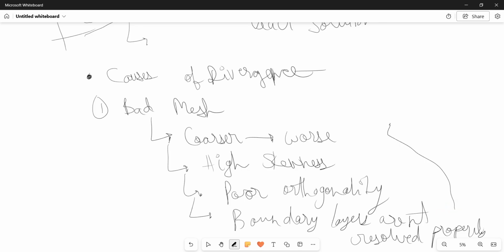I told you at the boundaries you need very fine mesh in order to capture everything like shocks etc. So if your y plus is too high, it means that your mesh is coarse around the boundary. This is something that you avoid, right? Especially if you're doing some transient and turbulent analysis, you should avoid a huge y plus value.